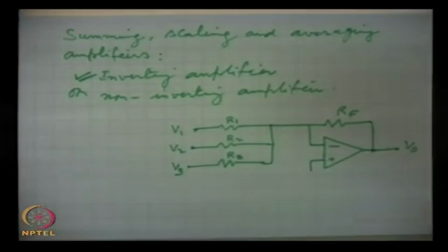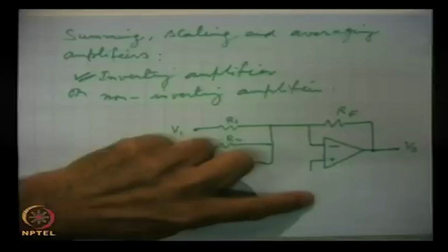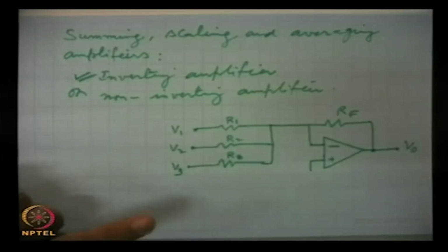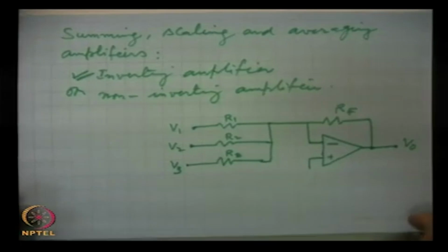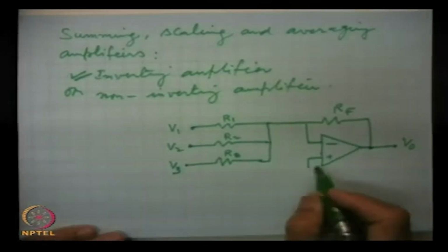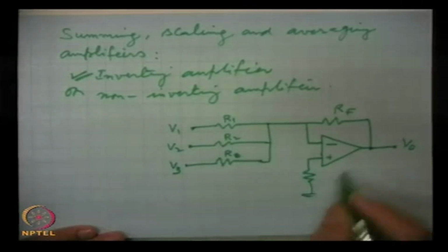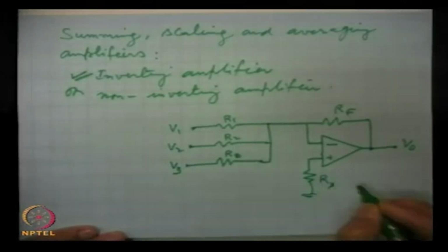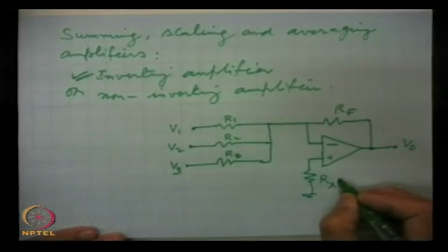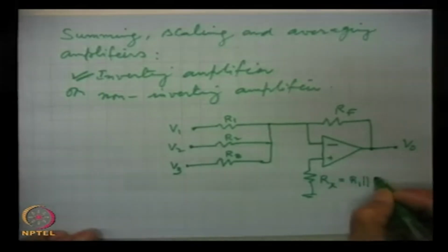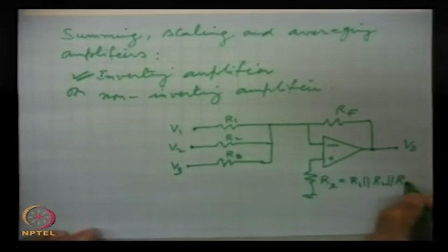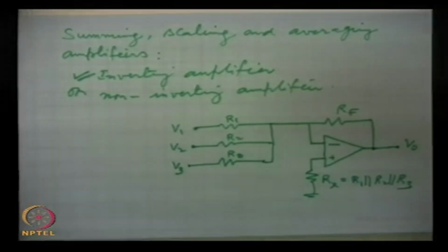So far we have been connecting it to ground, but now we introduce another concept. Instead of directly connecting to ground, it has been shown that if we connect a resistance Rx here, which is roughly equal to the parallel combination of all these resistances R1, R2, R3, it works better.